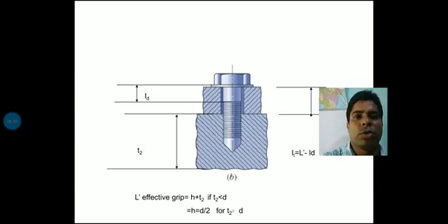more effort is required to disassemble this and this part. So in that case, we can tie it in a proper and limited way. Otherwise, once it is fixed properly and some certain gap is there, suppose the duration is long, some moisture and some waste will gather near the bolt.